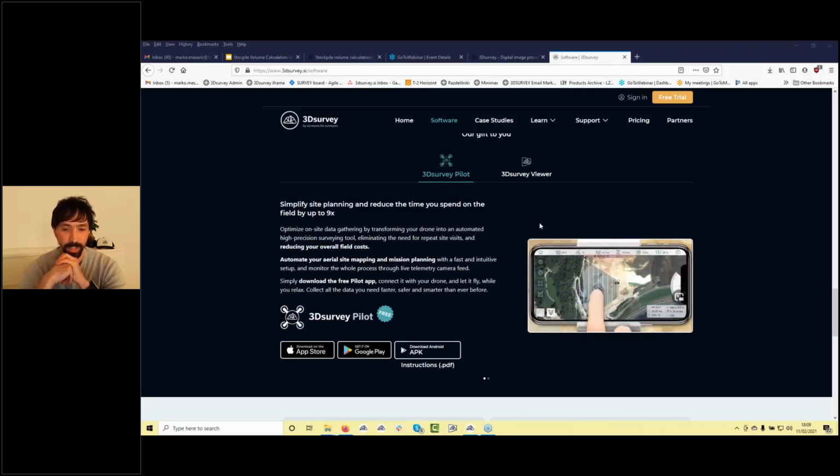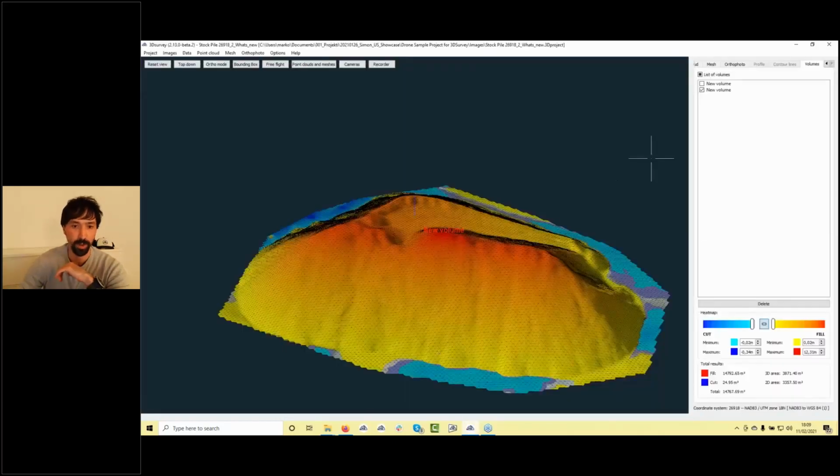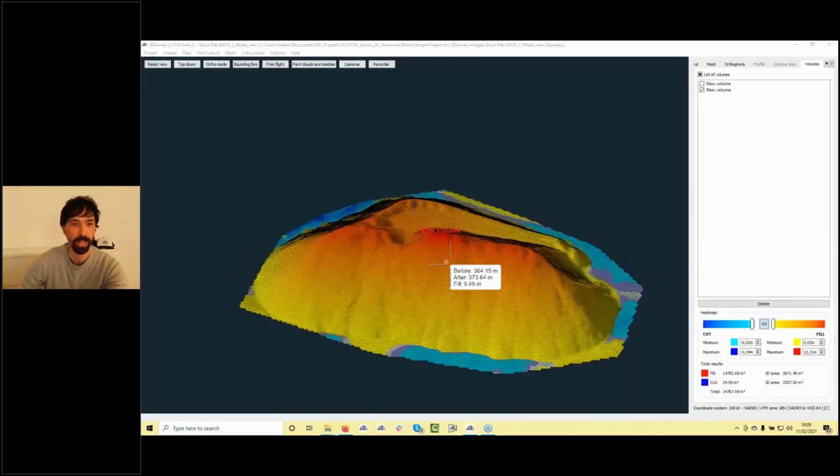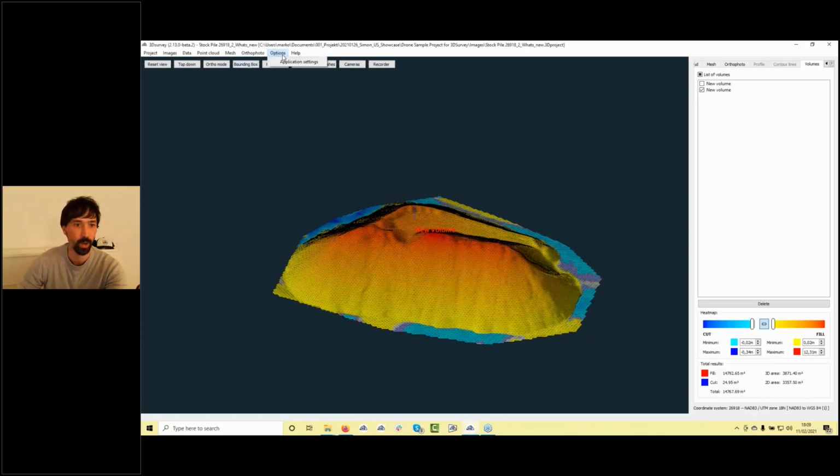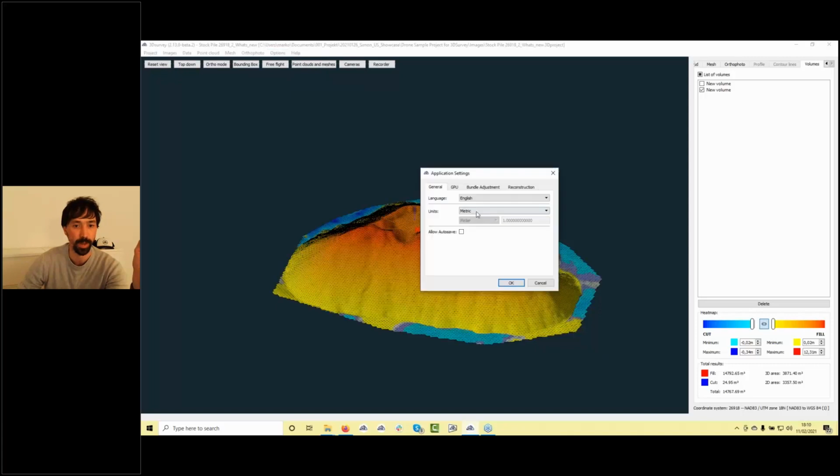Okay, then another from NG Jungli: Can volume units be changed when needed? You can see how I change the volume units. Everything is calculated from the data, so you need to change it in general settings, application settings, and go to imperial or metric. When you go to imperial, you have three options. In our case it was US survey foot.